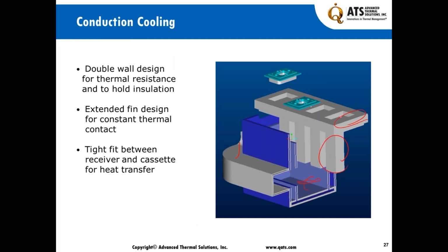likely on the convection side, depending upon how the system is designed, and equally as important, which a lot of us tend to ignore, on the radiation side. So I could have significant radiation heat transfer happening here as a result of this huge delta T, and it's going to impact my design. So I have to be cognizant of this as I go through the design in order to make sure that we've done this properly and we have not missed a beat.